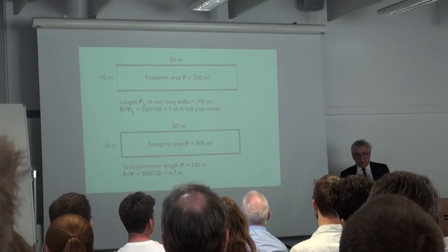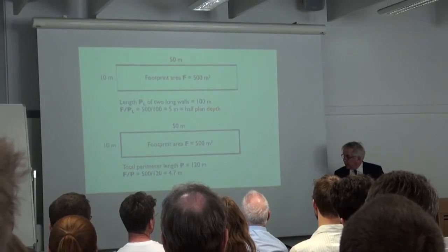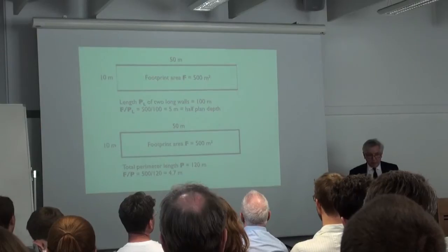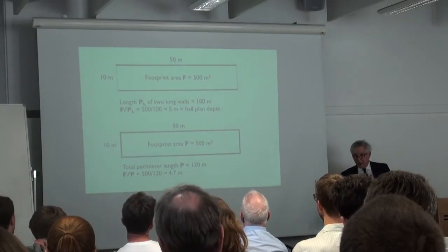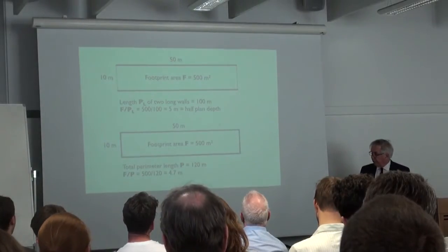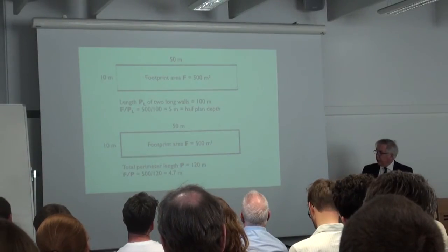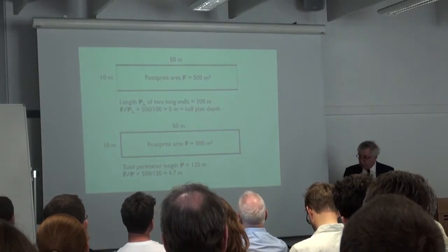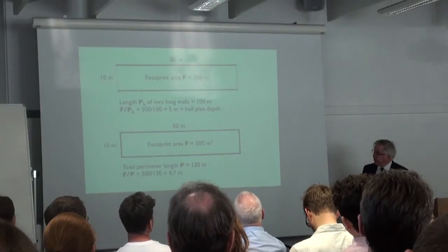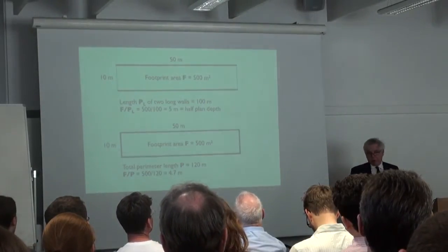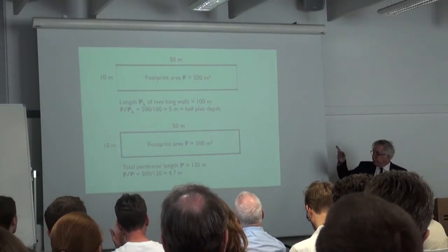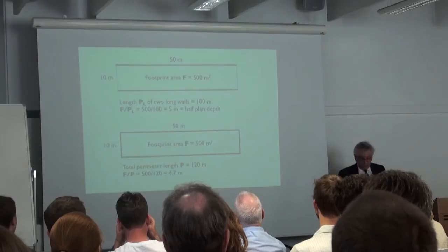The virtue of this, of course, is that one can apply the measure to buildings of any shape and get an approximate idea of their depth, which can vary, of course, in different parts of the building, but one gets an averaged figure. And given that many buildings, for real good reasons, tend to be limited in depth, particularly buildings that are day-lit, which I'll talk a lot more about, then, of course, built forms do tend to be extended either horizontally or vertically in order to preserve this depth, and so this is an appropriate way.